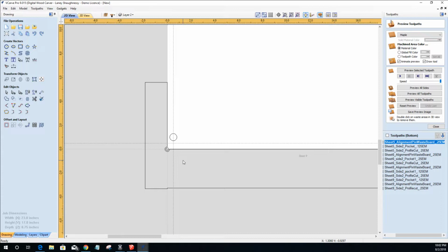The jig is more so for the placement of the board on the table than the squaring of the board. We want to make sure that the boards land in the exact same spot so we can use the exact same alignment pin holes. If I just free clamped my board and I zeroed out with my DWC Quickset, it's going to nail me right on the corner of my board each and every time.